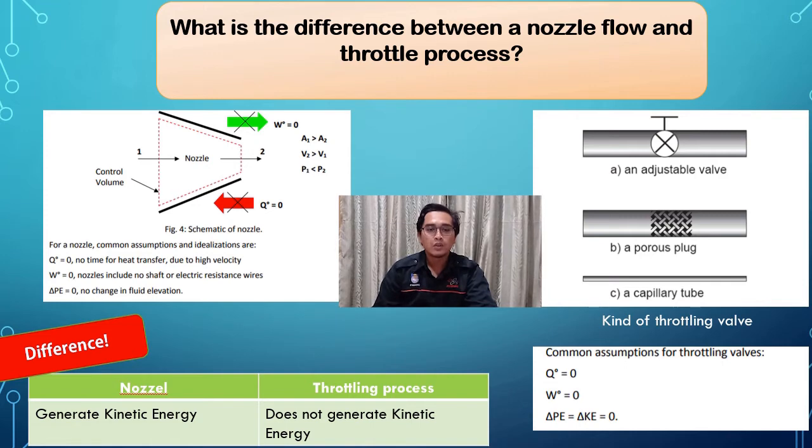Things like valve and orifice do not have the geometry needed to efficiently accelerate the flow. This conversion of pressure to kinetic energy determines if a restriction can be estimated as being isenthalpic or not. If we look only at the pipe and nozzle, we might also add in kinetic energy when trying to determine the local physical state of the fluid as it travels along the pipe.